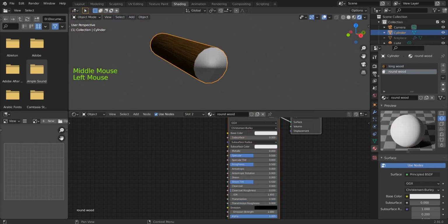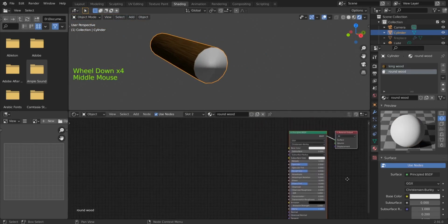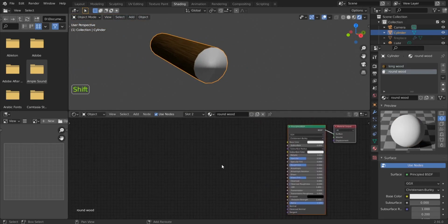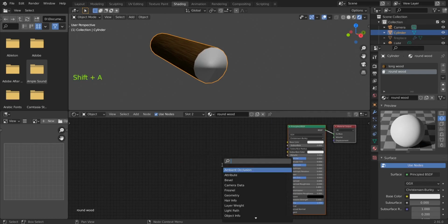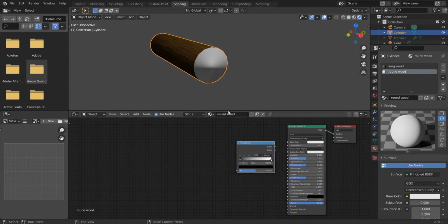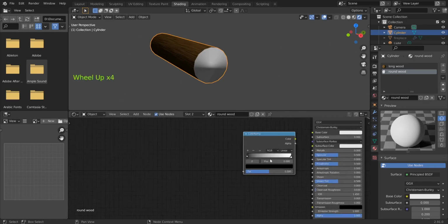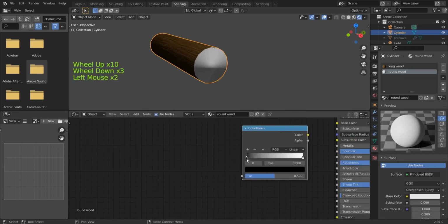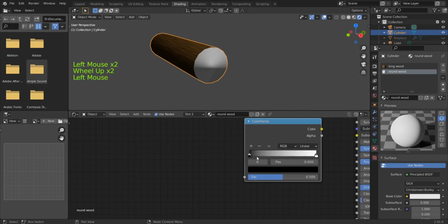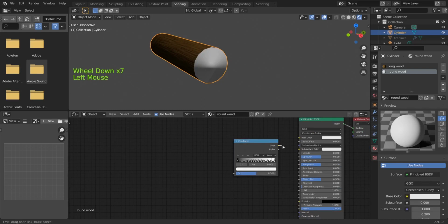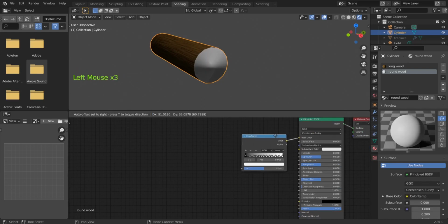Now we go to the second material. It's almost the same, but a little bit more complicated, especially in the color ramp. We want to have some circles in here for the wood. So we will first add a lot of color stops in here, with Ctrl click. Yeah, Ctrl click, and we add a lot of these like this. And then a color to the color base.